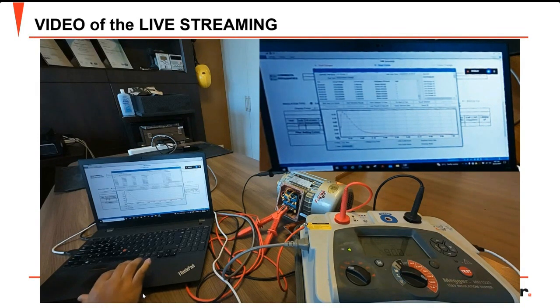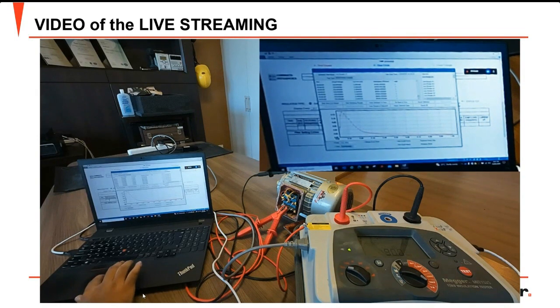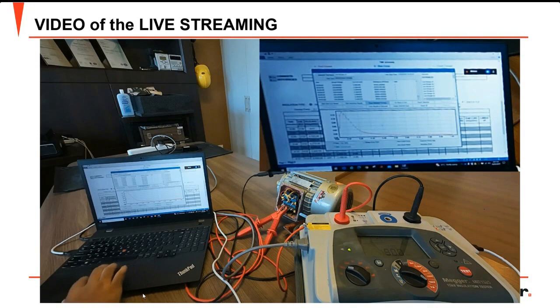But after a while, capacitive current is gone, polarization current is gone, so the current will go down, so the resistance will go up as well. So here you can import these values to the form if you want to. So you can click Save Selected to Form, and it will automatically fill up the form.